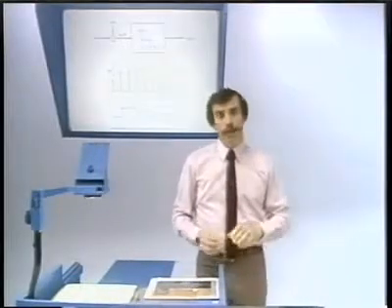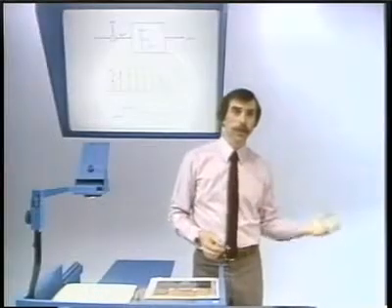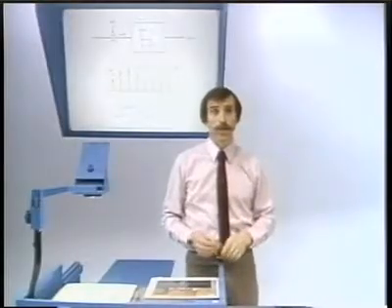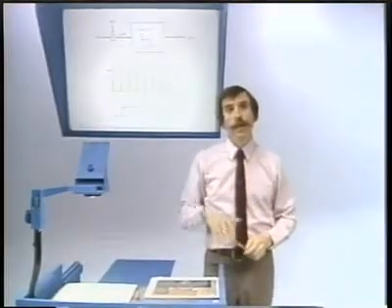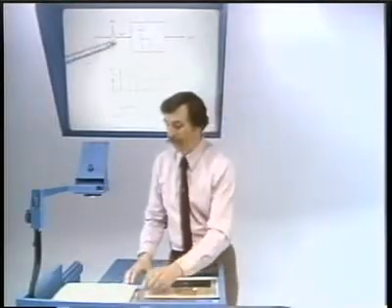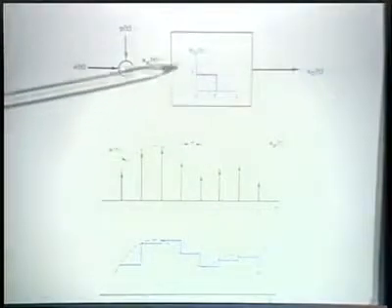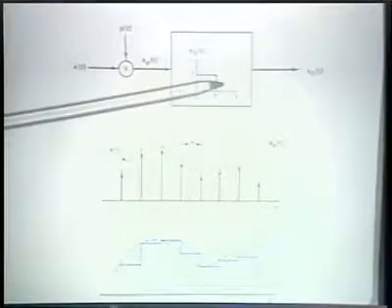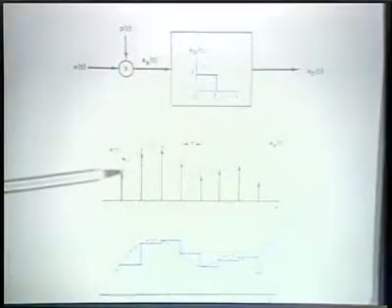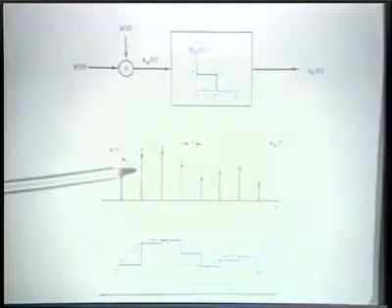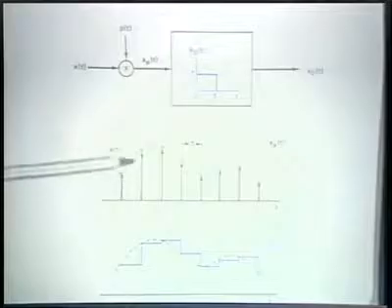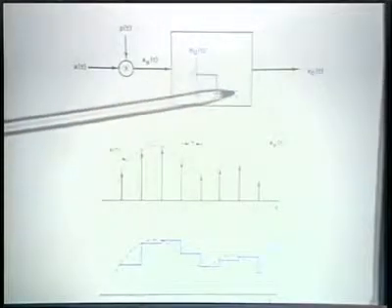Well, what I'd like to do is demonstrate, as we did with the band-limited interpolation, or the sinc interpolation as it's sometimes called, interpolating with a sine x over x. Let me now show the process, first of all, where we have a zero-order hold corresponding to this impulse response, in which case we'll see basically the same process as we saw in the computer-generated movie previously, but now, rather than a sinc function replacing each of these impulses, we'll have a rectangular function.